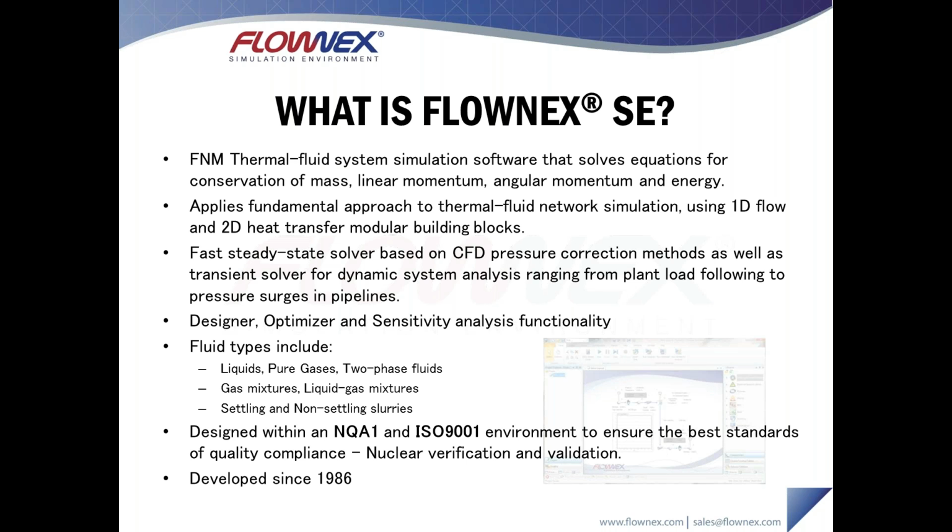The software itself also ships with a couple of analysis tools. So it has designer functionality, which works very similar to the goal-seek function inside of Excel. It can help when sizing components to achieve certain temperatures or flow rates, for example. It has an optimizer, which works similar to the designer. However, instead of designing for an exact value, it just seeks to either minimize or maximize a value. And then lastly, the sensitivity analysis functionality is used to vary a couple of input parameters and see the effect on other parameters inside of your system. So it's very good in the optimization stage of your design if you're looking to optimize many different variables.